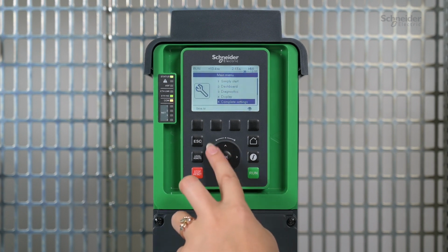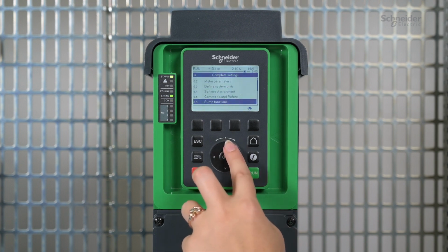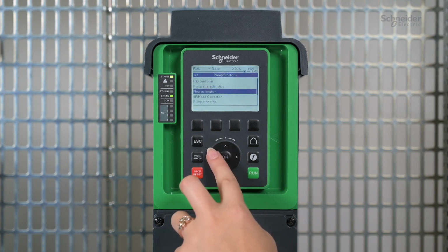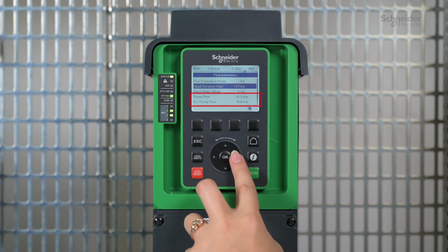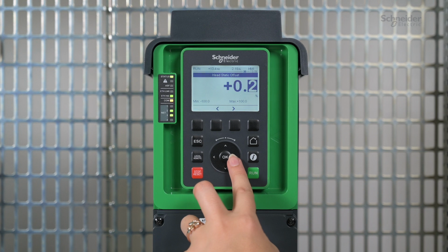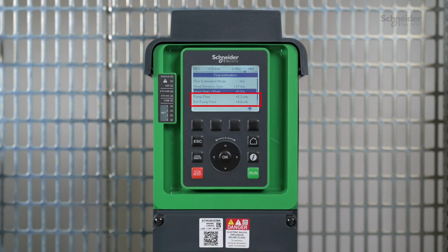Return to the menu, Flow Estimation. Set HEO so that the pump flow value reaches the estimated pump flow value. Stop the drive after calibration is complete. Note, this calibration is related to our system. During your calibration, you will not get the same values.